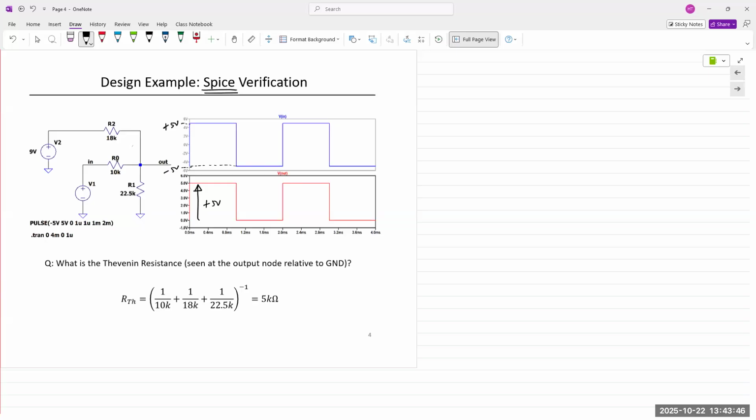The way we would do this in LT Spice is we would assign a voltage source V1. And in the advanced settings, you choose pulse. And in pulse, you specify, have you done this before for the lab? There was one nod and there was one shake. Okay, all right. So start voltage is minus 5.